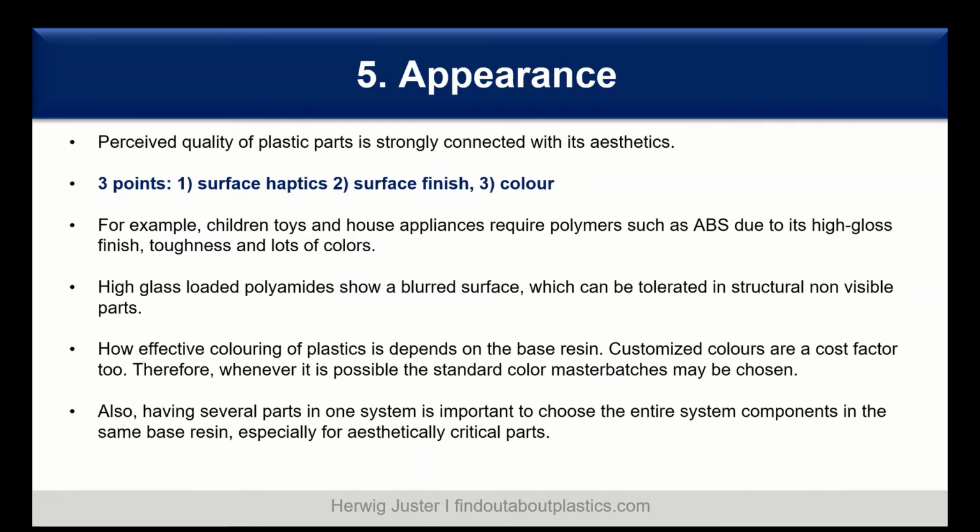And also when you have several parts which build up a system of components, it is useful to make all these components out of the same base resin if possible, especially for aesthetically critical parts.